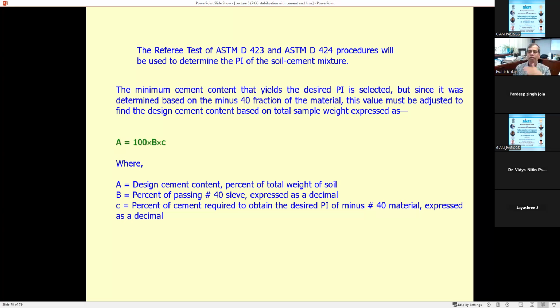You need to check the volume change and the loss of mass, and after how many repeated cycles, and then you can determine. So you cannot say it in advance. You need to do the test, and only then can you say how durable it is. Does it make sense?